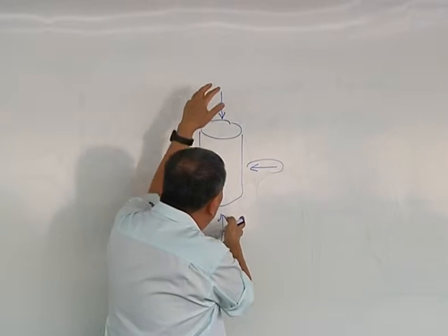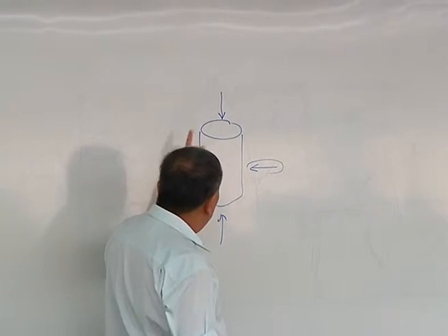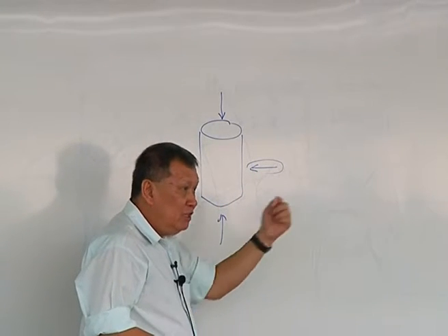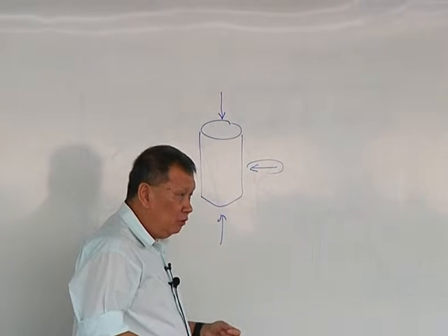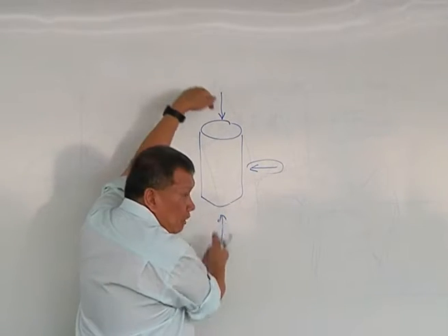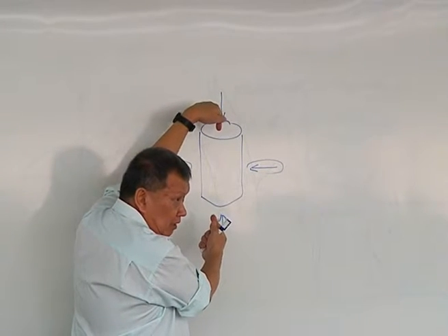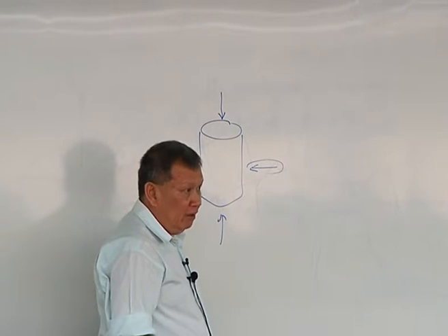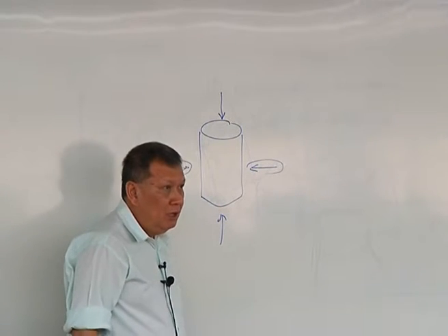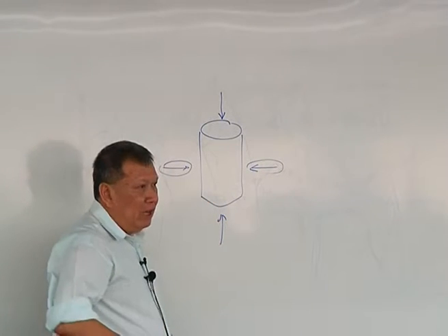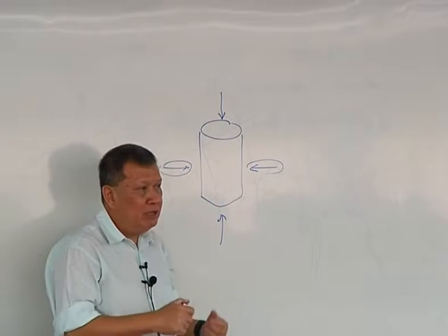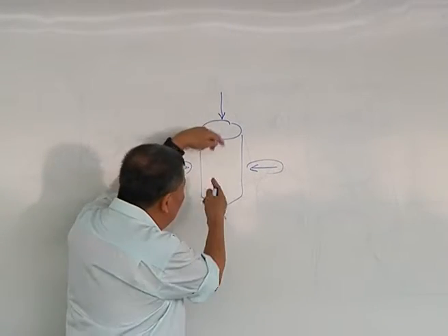Okay, the volumetric strain is only guided by one thing, and that is the P. So you have to take the average stress of the three normal stresses, and it will change based on that. So there's no requirement that the strain must be the same. Even if it is elastic, even when you start loading it back and you get elastic behavior, there's still elastic strain. You get elastic rebound. So I don't think it is likely that you will get absolutely zero strain. You will get some strain. It's a question of whether you get plastic strain. You will probably in the interim region get no plastic strain.